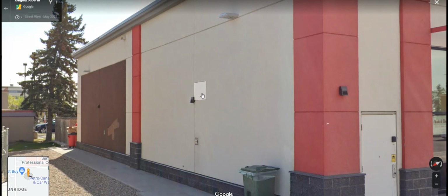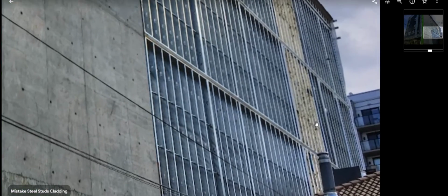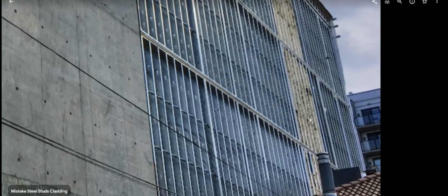And I'll just finish this video up with an interesting project I was watching get built. And this just demonstrates that you don't have to do the masonry wall. So I was biking around one day and I just noticed this building getting built, and I looked at this and I was like, oh, this is interesting. So there's a stair core or elevator core right there. So that's why that's concrete there. But then I saw that they were doing steel stud on this wall right here. And if you look close there, you can see there's some insulation going in the stud spaces right there.